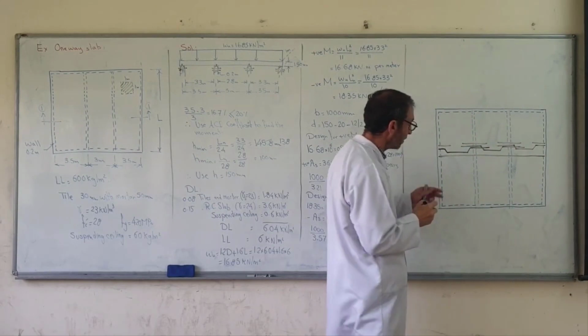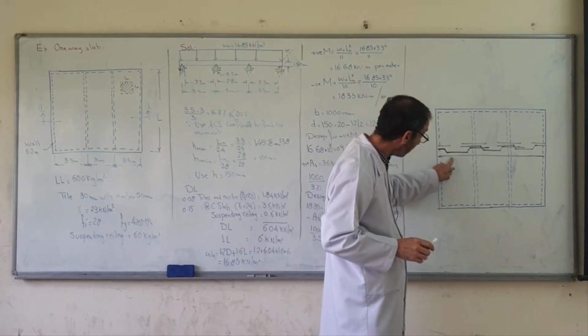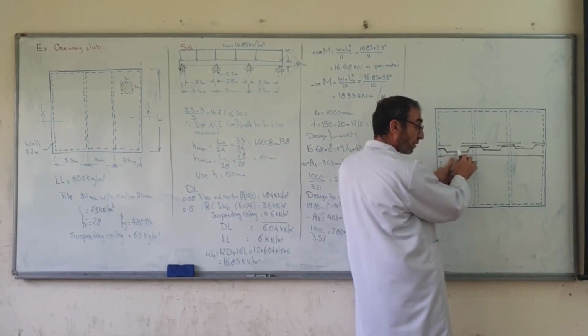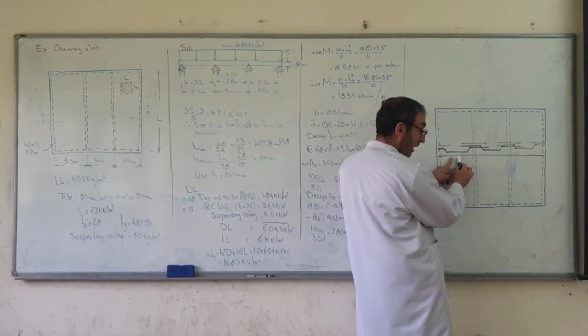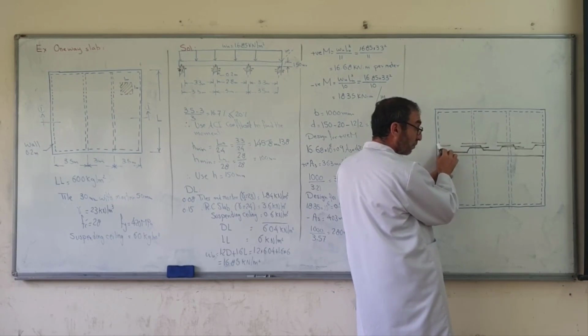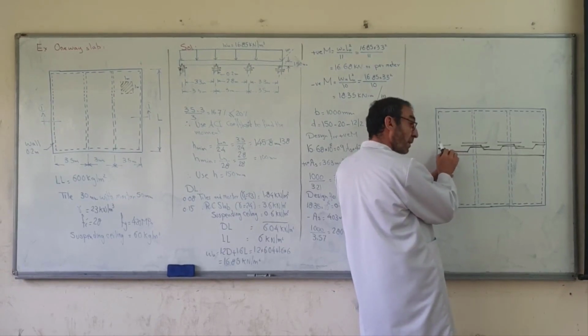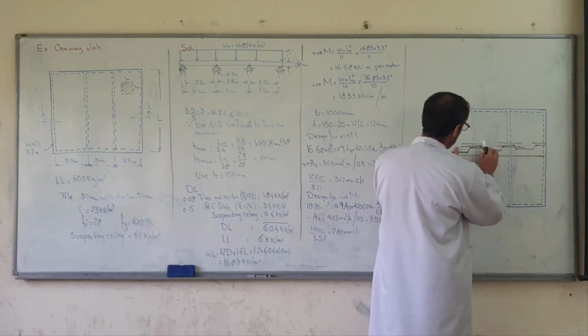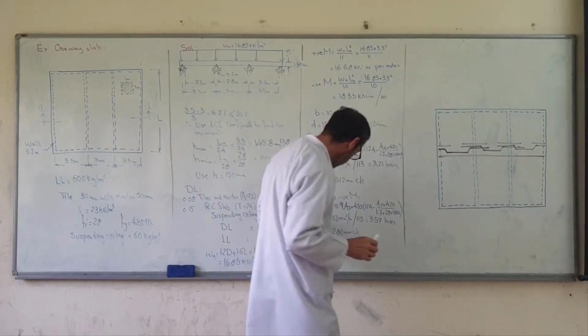This is the bent bar. We show the reinforcement this way. This is the bottom bar, and this is bent. Some of the bars participate in the positive moment at bottom, whilst others participate at the top as negative reinforcement. These are additional bars, and additional bars are required.